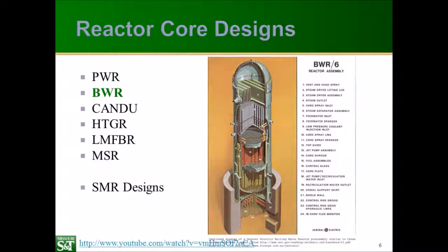You also have boiling in the core, and so on. And then in the steam line, we have to worry about heat loss and condensation because any water that condenses in the steam line will try to fall backwards into the core, so you have some countercurrent flow behaviors and things like that. We also have some important safety features here: steam isolation valves, the suppression pool, and then some safety relief valves in the emergency core cooling system.